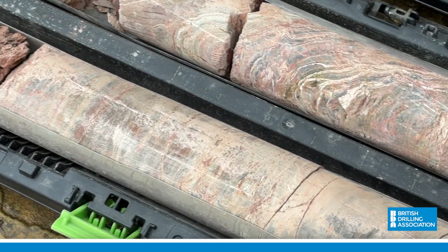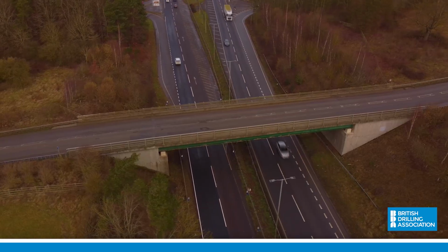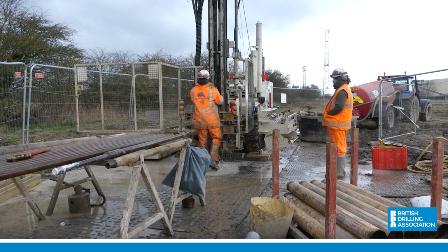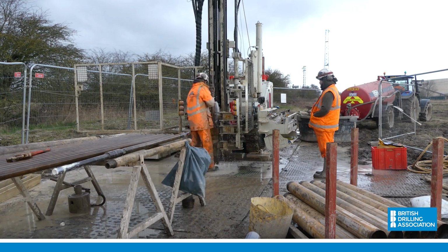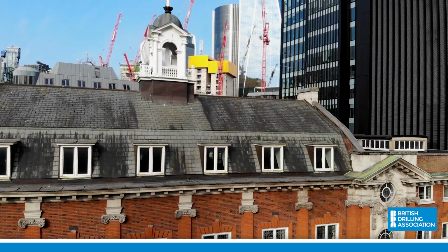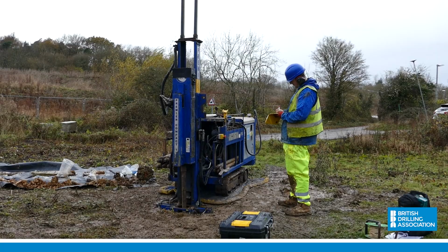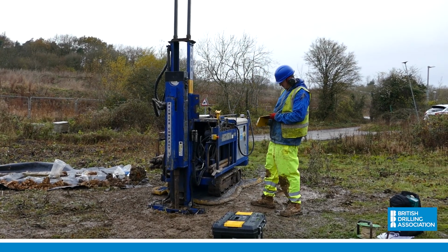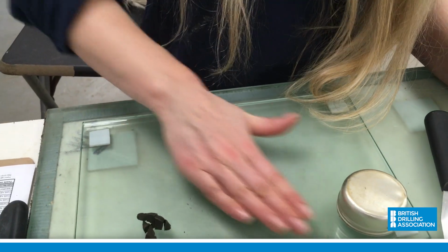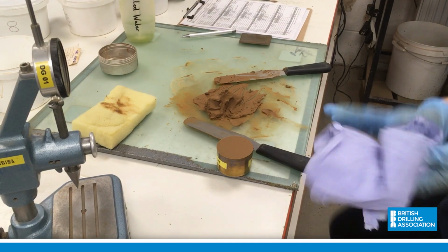All of these things are relevant to the performance of the strata in engineering applications, and ensuring we have an accurate picture of what is beneath our feet is crucial to ensuring the long-term safety and stability of the structures built above it. Characteristics of the ground can be obtained by in situ tests such as the standard penetration test, but more often they are taken from laboratory tests carried out on the physical soil and rock samples.